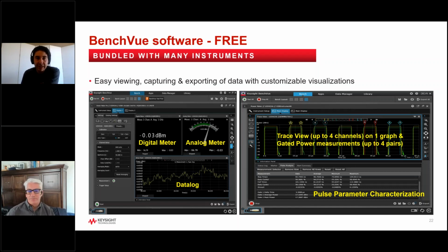I think you'll find the same SCPI commands. It's pretty ubiquitous. You do get some advantages too of just speed, because now you're not going through GPIB. But really, no code required for being able to collect all of these different types of measurements. So for those who have maybe moved away or don't want to necessarily dive into writing, sending, and controlling SCPI commands, the GUI is very straightforward and very easy to learn.